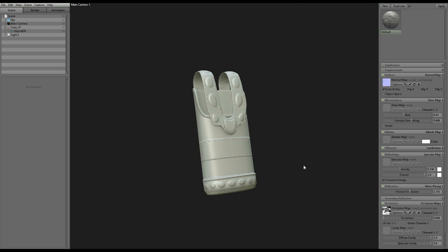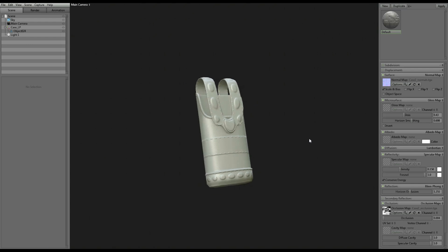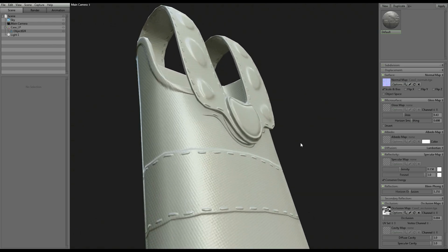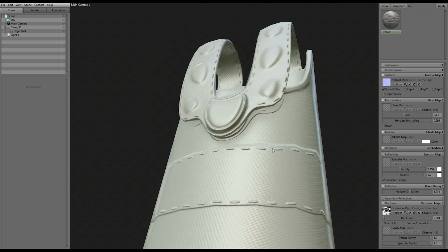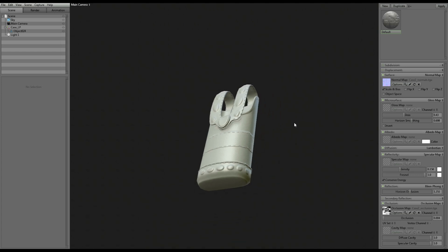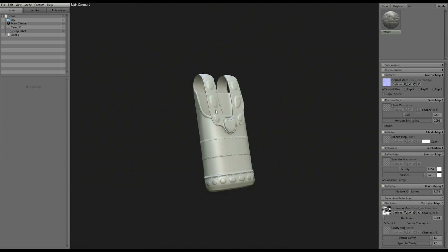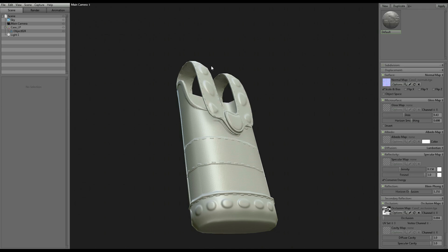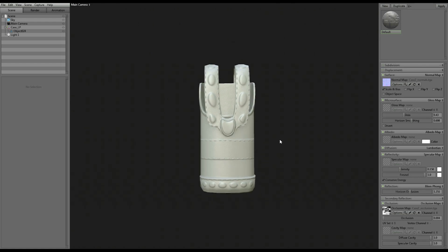But actually going to our test bake here in Toolbag, I'm pretty satisfied with the overall results. It looked about how I was looking for it to look. The only problem we ran into is right here. If you look right here, and hopefully you can see that on the video, I've got this sort of projection going on from the top half, and the reason that happened was because I'm not using a cage and I didn't explode my elements away from each other. So if you ever run into a situation like this, look for something like that, because this will happen. But for test bake purposes, we're fine.